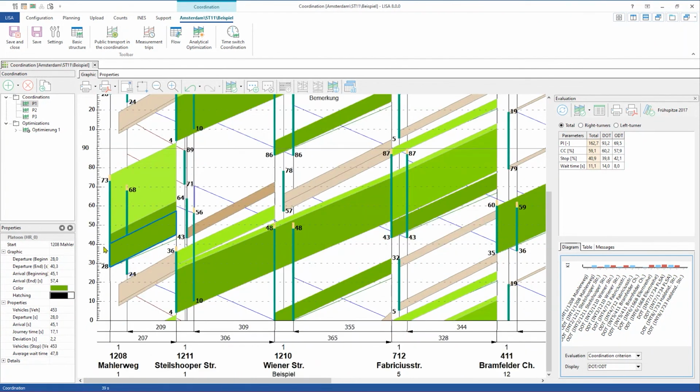The first platoon is all cars that arrived at red and will be queued back, and then at green beginning they started and have a really high density. So these are the cars arriving at red. The next platoon is the cars arriving at green, but they drove off this queue back of the first platoon. And the next platoon is all cars arriving at green. And you see that the color is a little bit lighter, so that means we have here a lighter density of these cars.